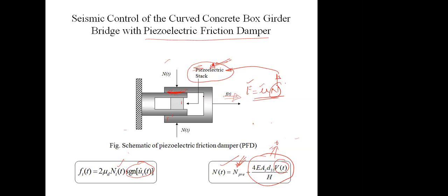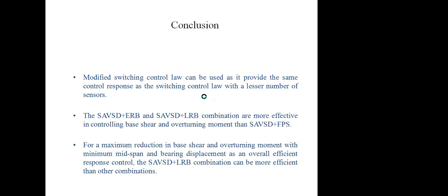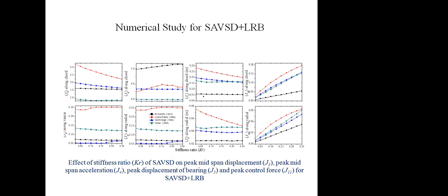Then from the mass matrix and the stiffness matrix we can calculate the damping matrix. We can assume that 5% internal structural damping is there. For that we can use a0 into M plus a1 into K. Using that formula we can calculate the C matrix, simple. By using the first two modes of vibration we can put the values of a0 and a1 there, and we can calculate the value of the C matrix. Then after calculation of the C matrix we can provide all the unknowns, like I will show you.